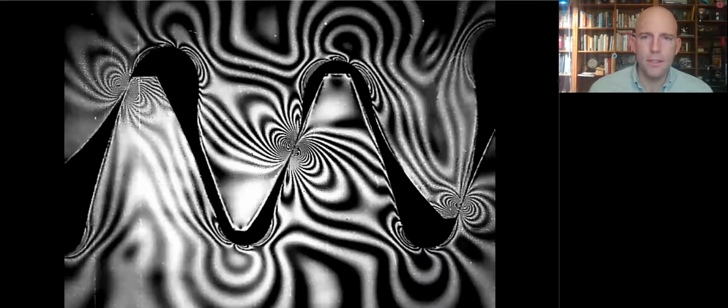Okay, here's a fun picture. This is an image of gears that are made out of a photoelastic material from ancient times, the 1960s. And the contours here correspond to regions of equal stress. So you can see that as we move across the line, say down here, probably the stress is pretty low. As we move up towards this contact point, stress is getting higher and higher until we reach the contact. And similarly, if we start here and move towards this little internal corner, the stress is getting higher and higher.